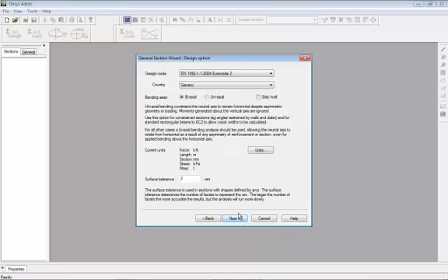And the idea again with AdSec is that, with ADC, you give the loads and the geometry, and it will give you the reinforcement. With AdSec, you give it the geometry and the reinforcement, and it will give you its load capacity. But also other information such as crack widths under given loads.